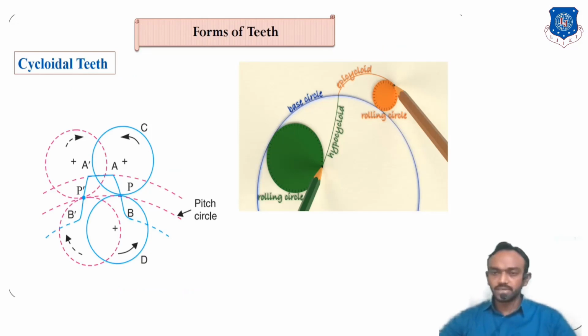It is the form of teeth. There are mostly two types of teeth, cycloidal and involute. So first check the cycloidal. You have already seen this cycloidal type profile in EG. Remember, try to memorize that. What is cycloidal? In cycloidal, you know that a cylindrical part rotating on a straight surface, if you locate a point, it makes a curve. It is known as a cycloidal curve.